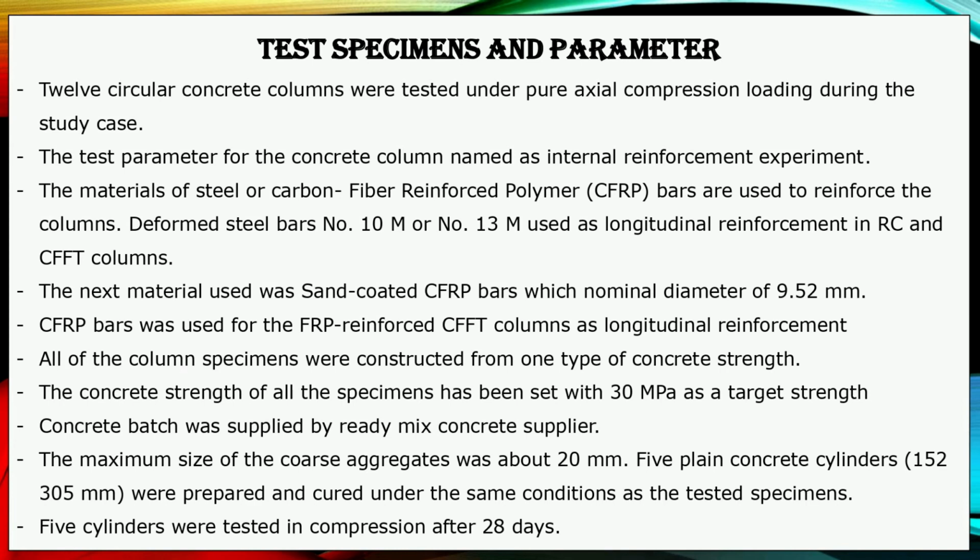5 plain concrete cylinders, 152 by 305 mm, were prepared and cured under the same conditions as the tested specimens. 5 cylinders were tested in compression after 28 days. The 28 days average concrete compressive strength was found equal to 30 plus minus 0.6 MPa.